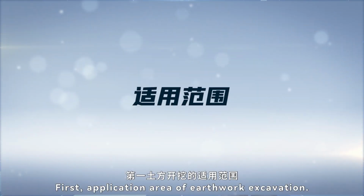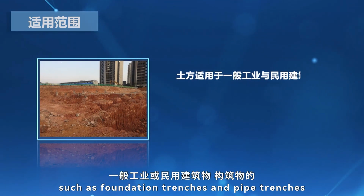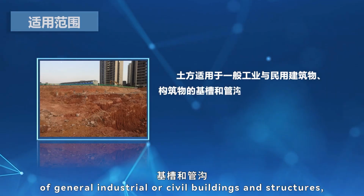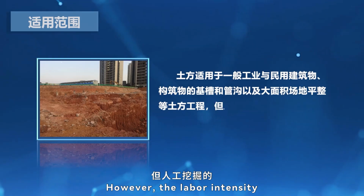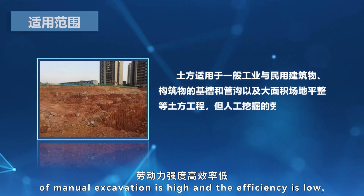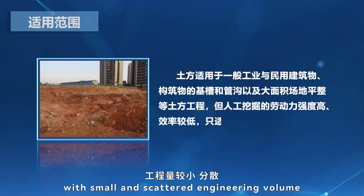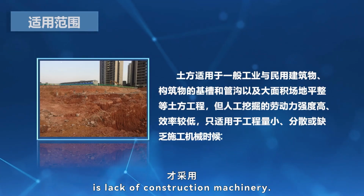First, application area of earthwork excavation. Earthwork is suitable for earthwork engineering, such as foundation trenches and pipe trenches, of general industrial or civil buildings and structures, as well as leveling of large area sites. However, the labor intensity of manual excavation is high and the efficiency is low, and it is only suitable for the engineering with small and scattered engineering volume, or is only used when the site is lack of construction machinery.